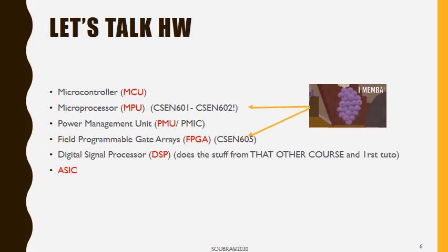All right? So you can go ahead and buy a microprocessor. It's not useful if you don't connect it to a memory because it won't get its instructions, and plus it needs to connect with the environment, whatever that environment is. Could be a keyboard, mouse, screen, whatever. You'll need some I/O module. Unlike a microprocessor, a microcontroller is a whole package. It has a CPU, an I/O module, and a memory, all in one.